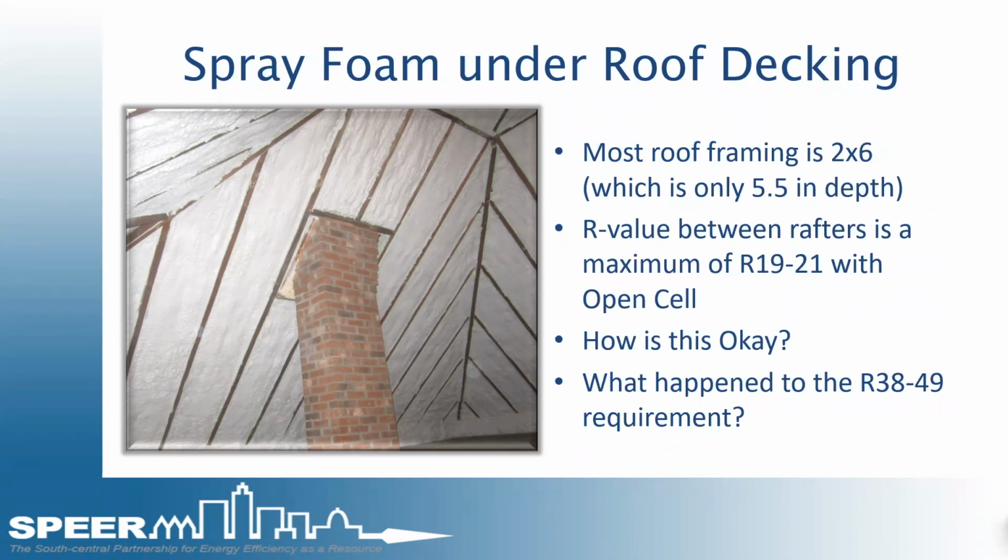It comes down to the energy model itself. From when I was doing the inspections, I know the engineering department basically stated that anything that was foam, they had to use the ERI calculation pathway, because the performance path did not have the right calculation engine to actually understand foam. In other words, it would fail the house if it didn't say R38. ERI would look at it differently. It allows for the trade-offs, and the calculations were done correctly.